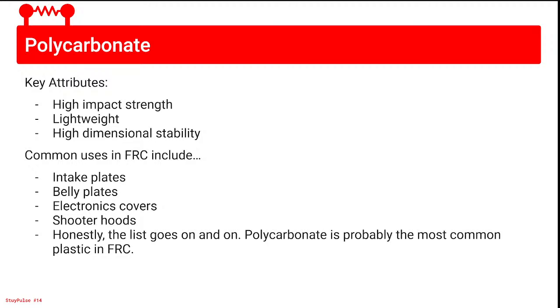One thing, the most obvious one, the belly plate on this robot was 1/8-inch polycarbonate. We've used polycarb belly plates for a while because we wanted to save weight. This was back when we were always about 0.1 pound away from the weight limit. So every pound counted. But we faced the consequences of our actions at the championships. So it's not complete anymore.